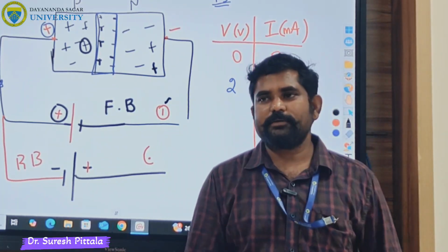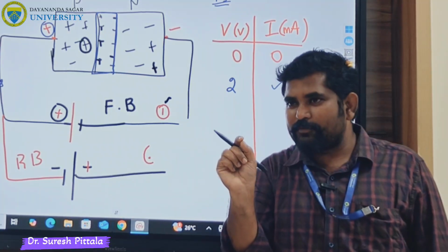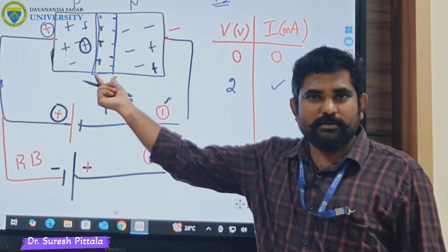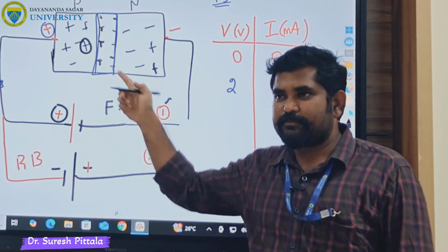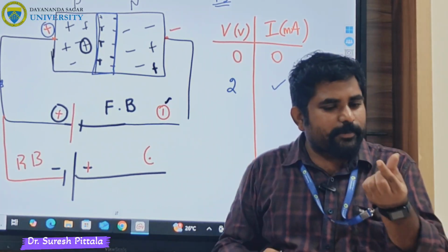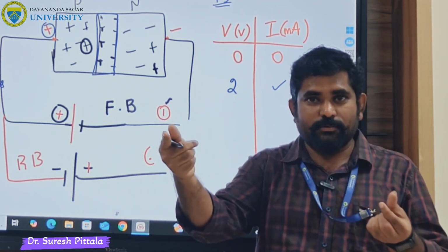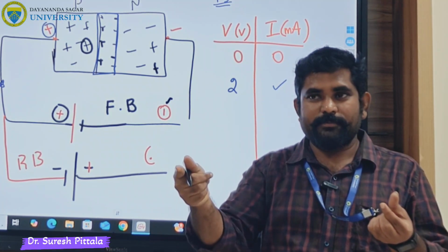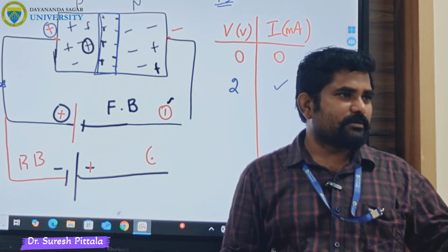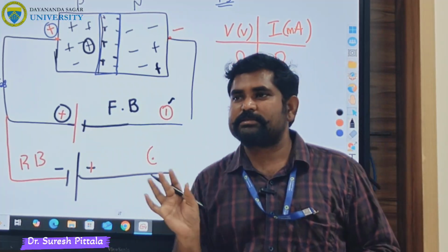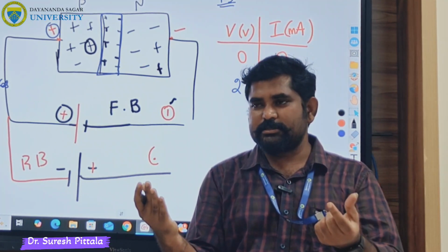You are going and connecting. Without supplying, nothing is there because a gap is there. So the moment you supply a little bit, 0.1, it will see whether it is sufficient. Look, the charge only moves when it gets sufficient energy to go from here to there. Therefore, sometimes you apply 0.3 and may not see anything because it is not sufficient to overcome. You have to understand why the reading is not coming. Something happened, don't just tap. Understand, everything has some meaning. Okay, I increased to 0.5 and I am not seeing anything. Understand, the depletion layer is still stopping.